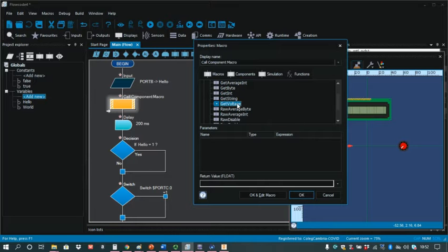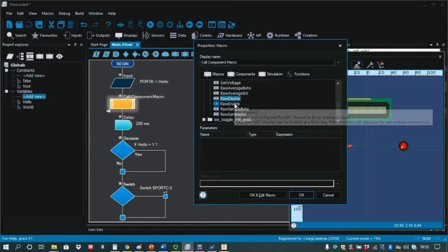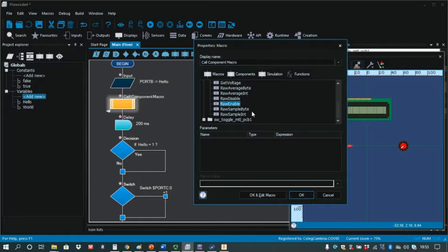The one I tend to use most is get voltage, which if I'm reading a battery voltage, then I can read in a 5-volt battery and it reads 4.7, so I know it's close to being fully charged, for example. We can get the raw average byte and the raw average integer, which aren't very much use. We can disable the raw and we can enable the raw, and we can also take a raw sample byte and a raw integer. So those pretty much double up on what these are. It's just a raw value as opposed to a digital value.